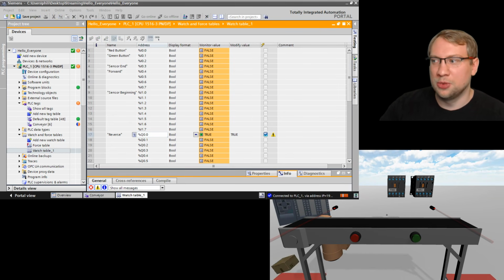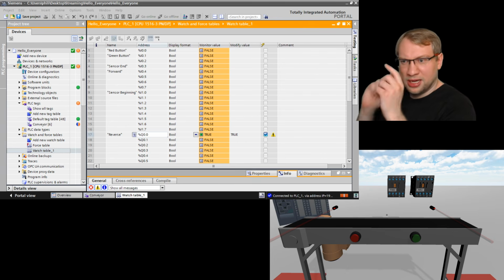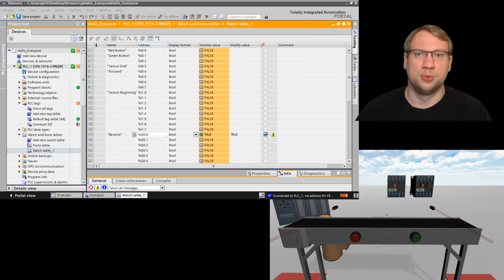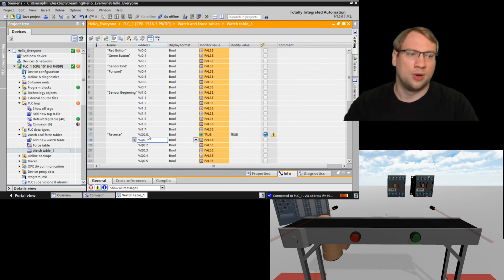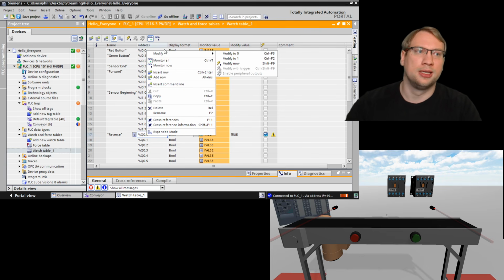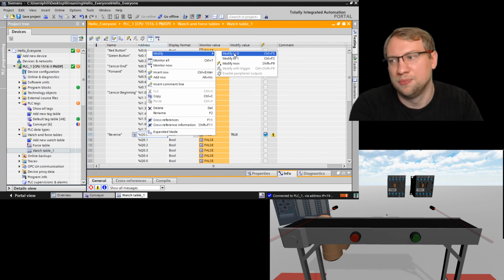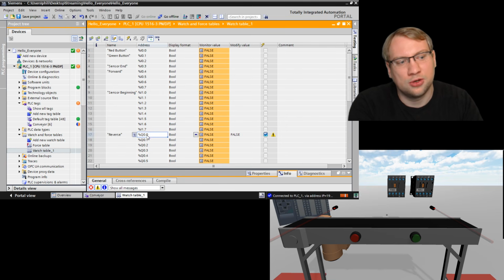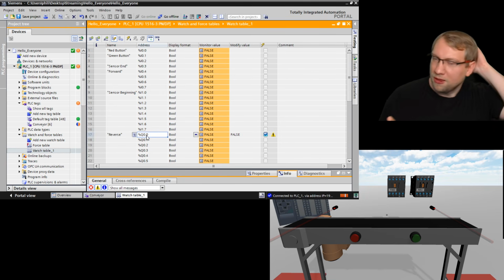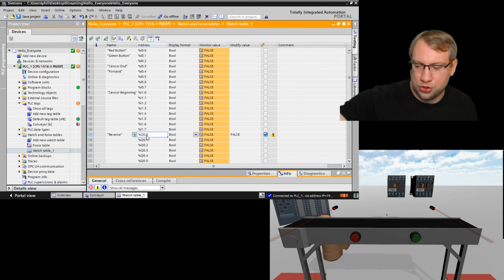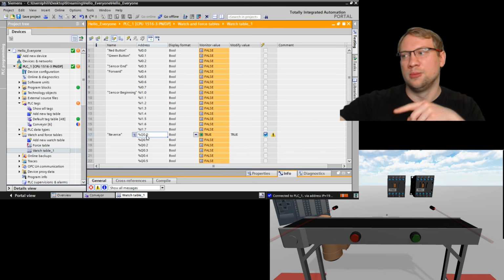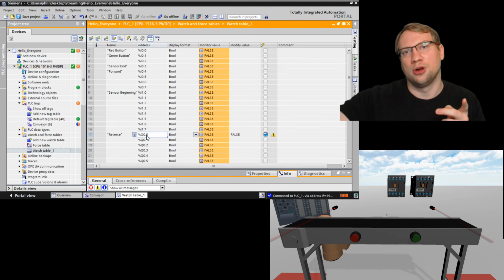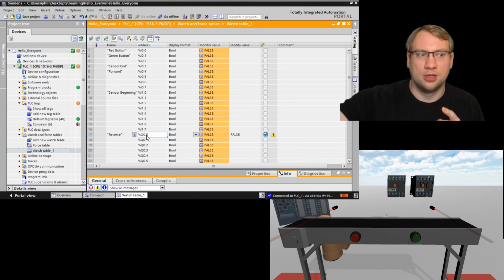So we're done with the reverse stuff and the sensor in the beginning. What do we need? The other things. So I will turn this back off, right click, modify to 0. There's also a very useful shortcut: Control and F2 will turn a variable to true, Control and F3 will turn it off. Control F2 is on, F3 is off.